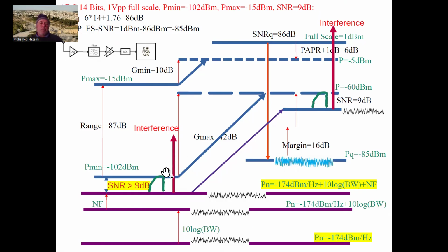And as soon as you get that, of course, boom, everything you built is just down the drain because, like in this case, for instance, it's displaying that this is your desired signal in the green. You got it, but then before you get to drive level, your blocker or the interference has clipped and has saturated your ADC. What do you do then? Okay, in this case, in here, I may not be able to filter because it's so close to the input signal. So what do you do in this case? And that's really an issue that we have to look at in the next sessions.